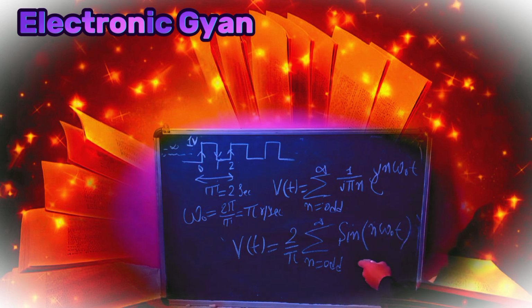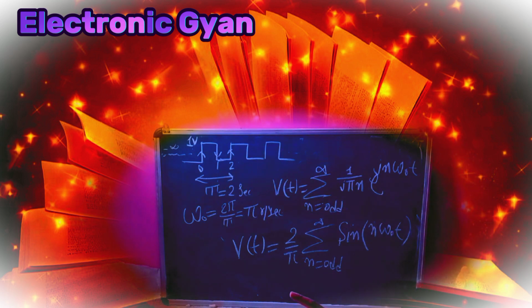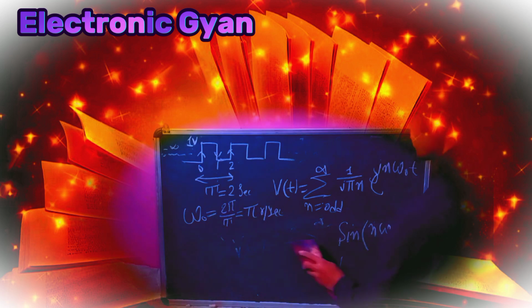This is sine omega naught t plus sine 3 omega naught t plus sine 5 omega naught t plus so on. So finally we got the Fourier series expression, the sinusoidal and harmonic expression, for this periodic pulse that we have applied to the low pass filter, where omega naught is nothing but pi.